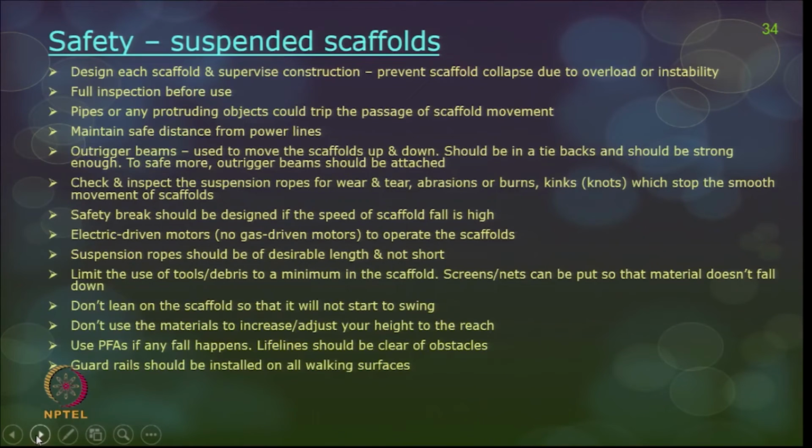Now, we will talk about the safety precautions. Again, as I told, all scaffolds should be designed, constructed and erected under the supervision of a skilled person, and you should take proper care while designing and constructing these scaffolds. Design each scaffold and supervise to prevent scaffold collapse due to overload or instability. There should be a competent person who does a full inspection before using the scaffold, and every time you start using the suspended scaffold, it should be fully inspected and only then used.